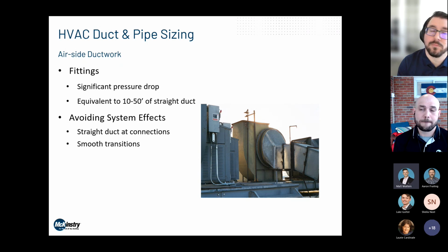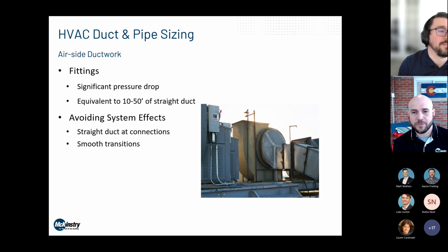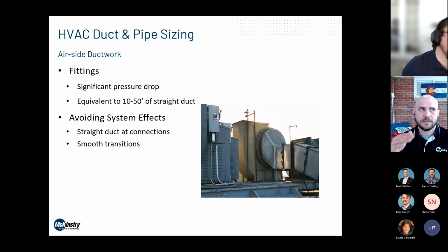Is that equipment volume known and given by the manufacturer, or how is that determined? Yeah, that volume will be given by the manufacturer. I will say that of those different types of airflow systems, the medium pressure duct is going to be noisier generally. As a rule, that's going to be louder. So if you have that passing by a space that is going to be more sensitive to sound, then something like a sound attenuator upstream of it passing by that space would be probably advisable.